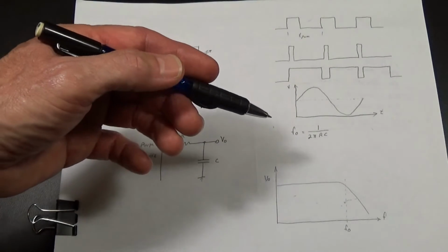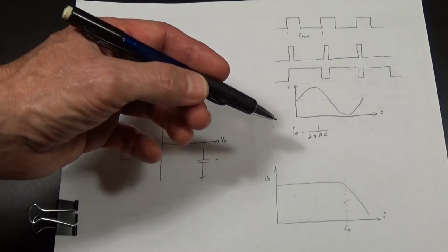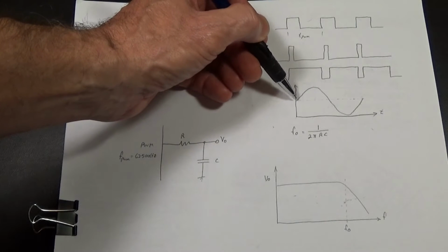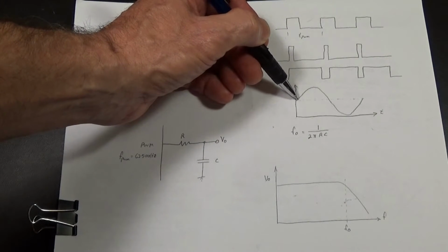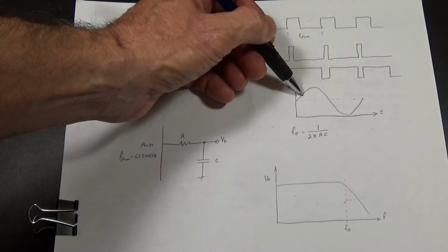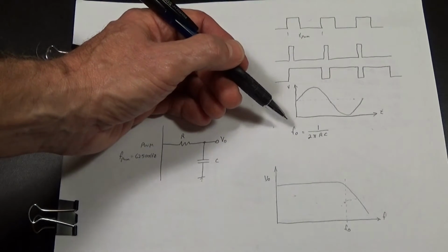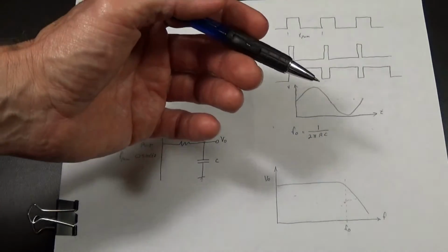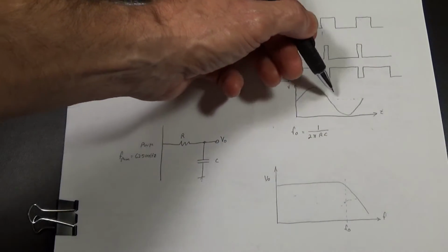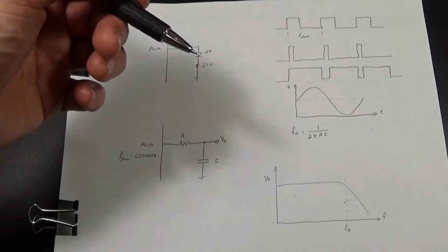So that's the way this counter works. If I just added one each time to the counter, it would go one sample after the next, and we would generate a very slow sine wave. But if I skip some of those by adding a bigger number than 1, then I start picking off different points along the sine wave.